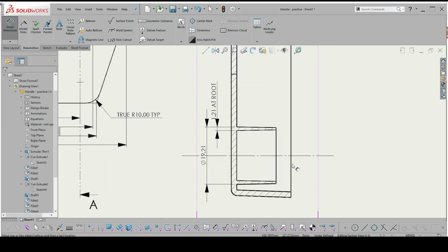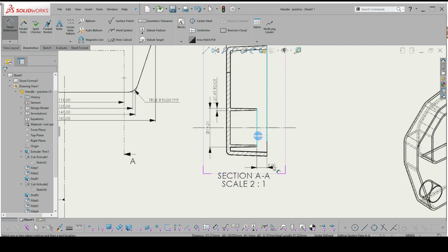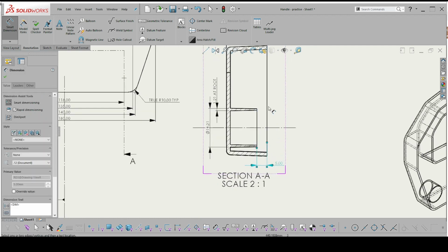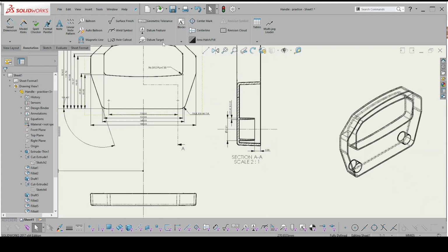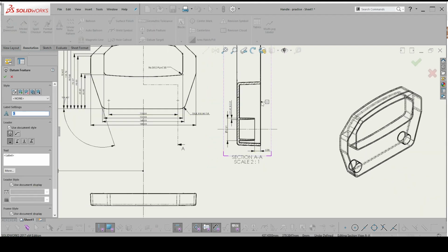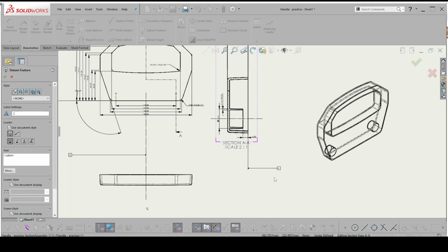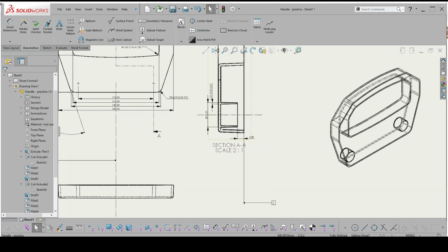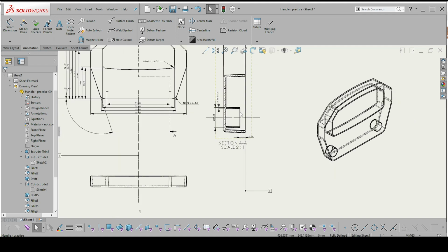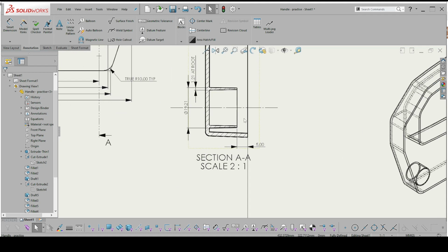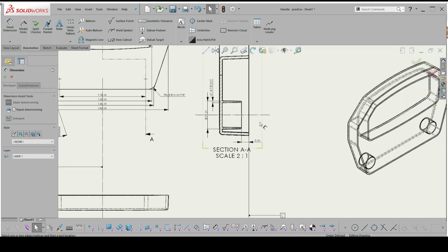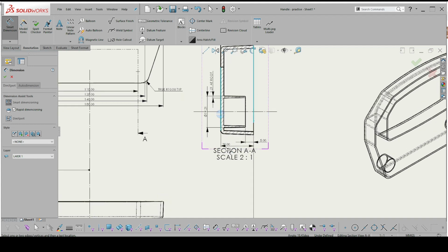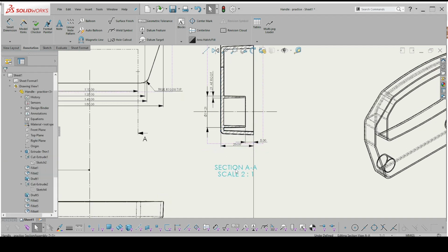Bingo. Oh, and the other thing I do need is to know how far away from the datum this rib starts. Remember, that's the datum. Oh, I haven't put that in, have I? Datum feature would obviously be this plane here. It's obvious because that would be the split line between the two mold halves. So that's my third datum. And I need a height. So I need to go from there to there. That's 20. And let's just move that out the way.